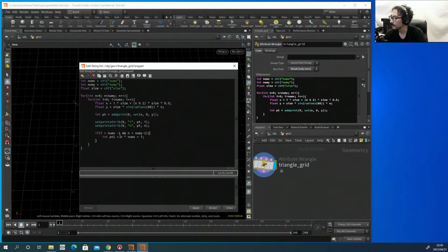Okay, so you can convert these n and I to a point number like these as well, which as a result you should be able to get the next point number on the x direction and the next point number on the y direction. So for the next x direction at the same row, it is going to be the same multiplication, n multiplied by num x and added by I plus 1. I plus 1 determines that you have shifted to the right side next to the current point. So this is going to be the next point number on the x direction.